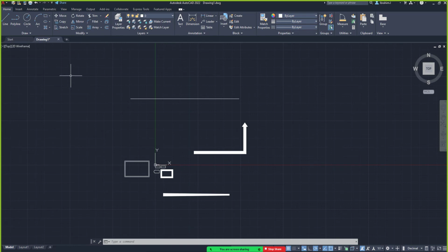Are you with me? So going with our line command, you can see instead of going to just activating our command there, I can just go to my command line and then just type line, L-I-N-E. Immediately I do that, even while you are typing, it's not compulsory you have it spelled completely. On the list, immediately you are typing out, there's always an option on the list. Can you see the list that is showing here? So I can just quickly go to my line command and click on enter. Immediately my line command has been activated and I can continue using my design.